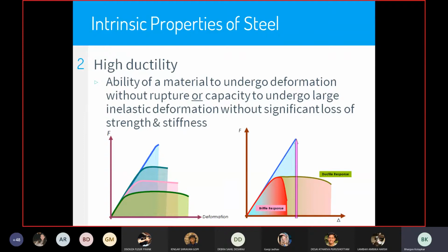It is similar to this. We are looking for a material that not only has good strength, but also has good ductility. And our stress strain curves give us a sense of how ductile that particular material is. If I look at the left figure, I've just given some random graphs of materials that have a certain strength and a certain ductility. You don't know the numbers, but when you look at that graph, you can say that the material with the green graph has the highest ductility, and the material with the blue graph has the highest strength. In a nutshell, the stress strain curve is a measure of the ductility of any material.